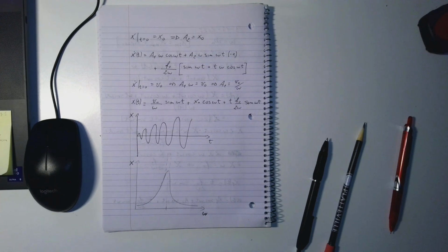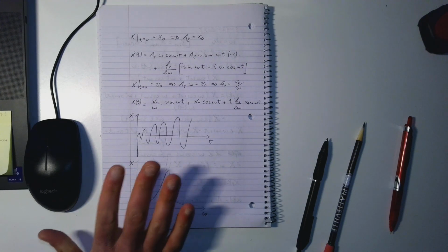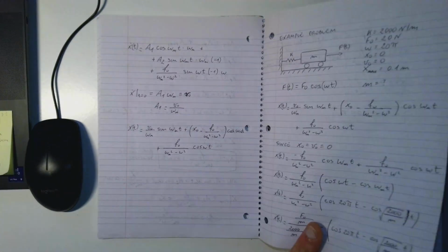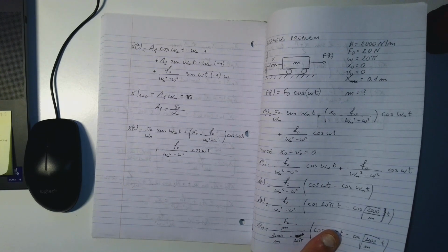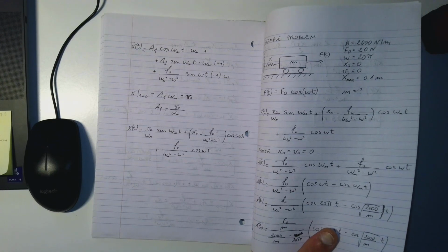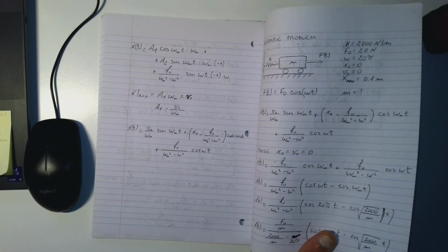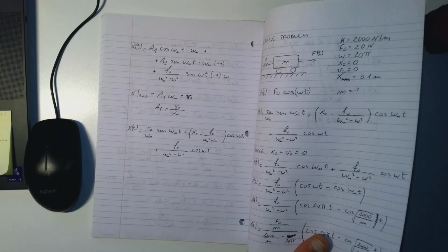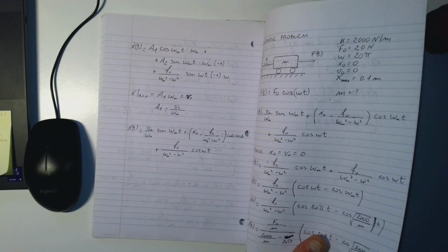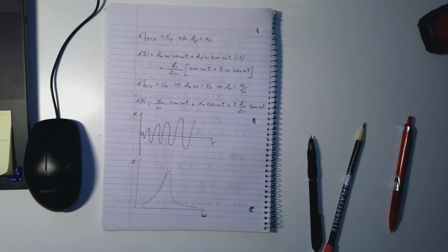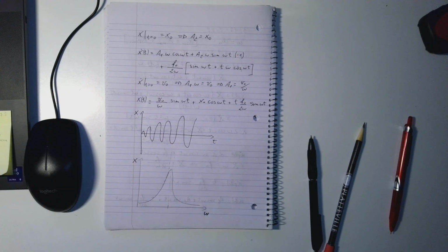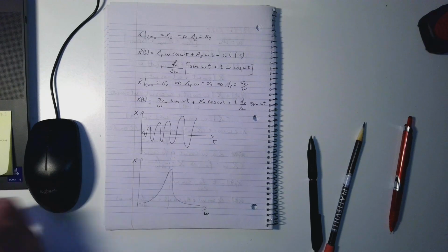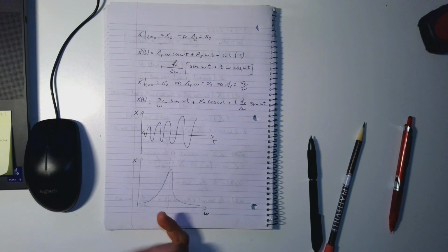Well, in that case you would find an equivalent stiffness and an equivalent mass of your structure. Again, we are now analyzing a structure made of one single mass and one single spring. Of course, this is an idealized situation, but in reality, with discrete systems, you will have multiple springs and multiple masses, in multiple degree of freedom systems. For continuous systems, like a beam, which could be a composite, for example, because concrete is a composite material, you would also find an equivalent stiffness and an equivalent mass, and from those you can estimate the natural frequency.